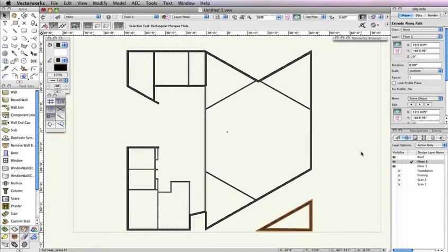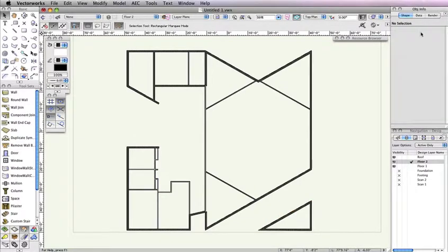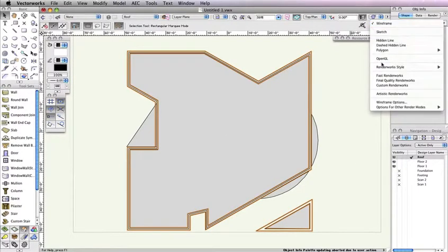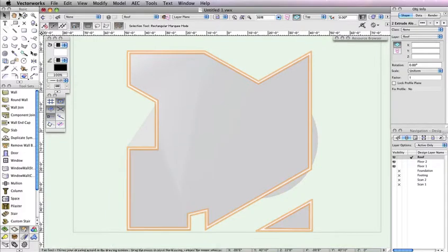Now, with the newly created extrude along path still selected, set the Z field to -1 foot in the Object Info palette and press Enter to lock in that value. Lastly, choose Roof from the Layer drop-down menu to move this extrude along path to the roof layer with the other roof objects and the roof flashing. You can verify this by making roof layer the active design layer, then rendering in OpenGL and using the flyover tool to see what you have so far.